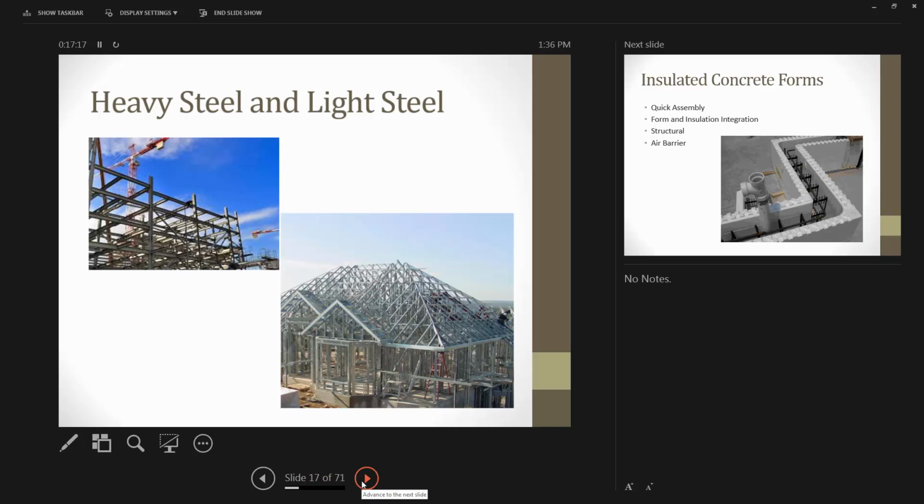When you talked about conductivity, you looked at the metals and the steels, and some of them have K values of 1,000 to 1,100, where you're looking at 0.3 for wood. So with any kind of steel, there has to be a thermal barrier on it. You've got to wrap it and put supplementary coverings on it.